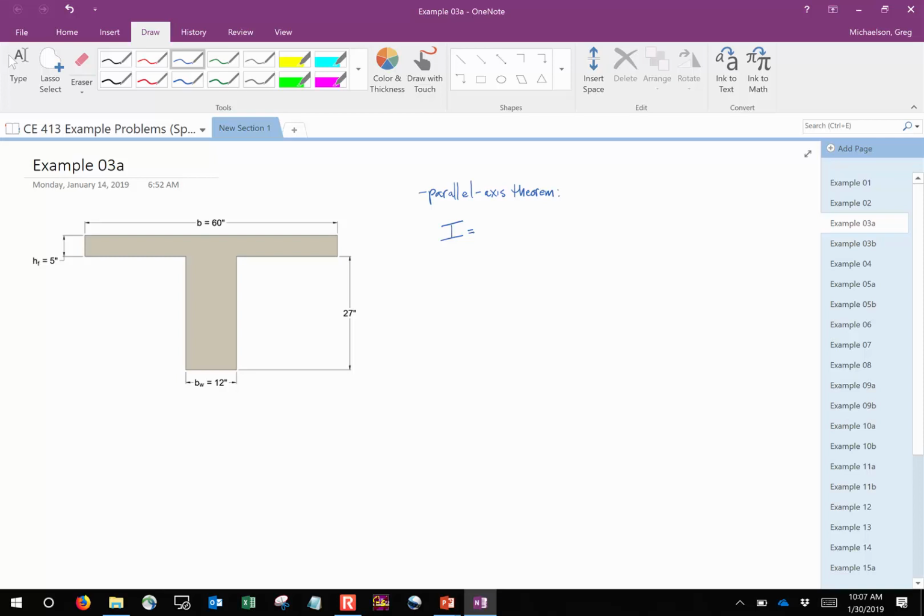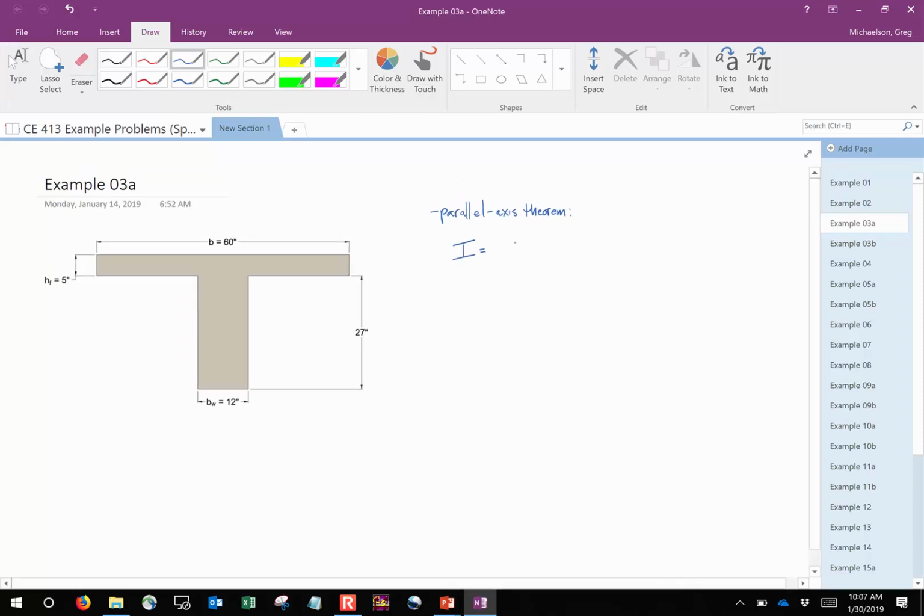So to determine the moment of inertia of a composite shape, what you do is you sum the following quantity. You say, I'm going to sum up the moment of inertia of each individual little shape plus the following quantity, A D squared. Now, area A is just the area of each individual shape. D, we'll get to that here in a second. I don't want to get overly convoluted, especially when this is a review, but don't worry, we will get there.